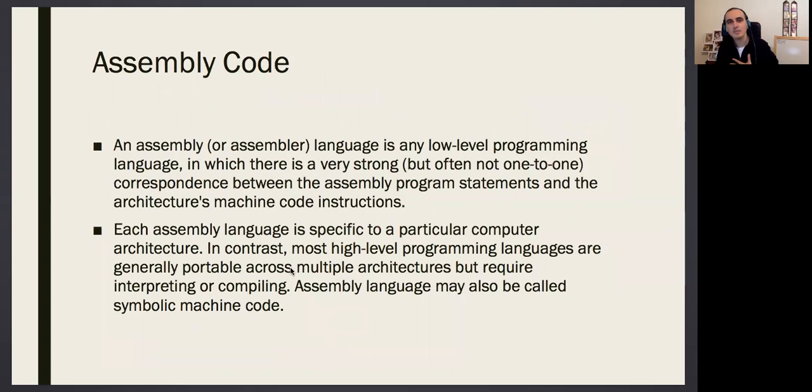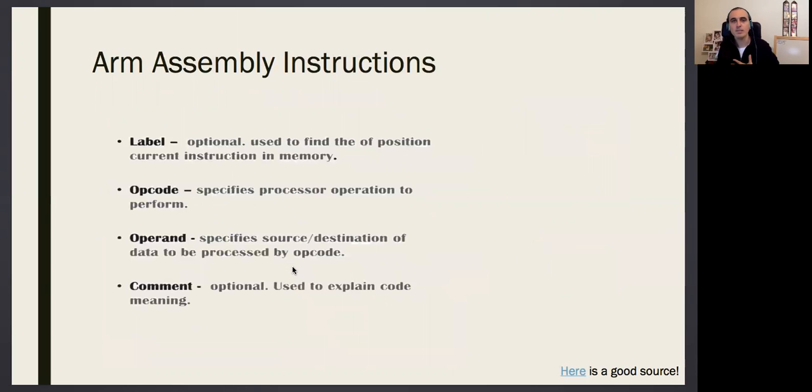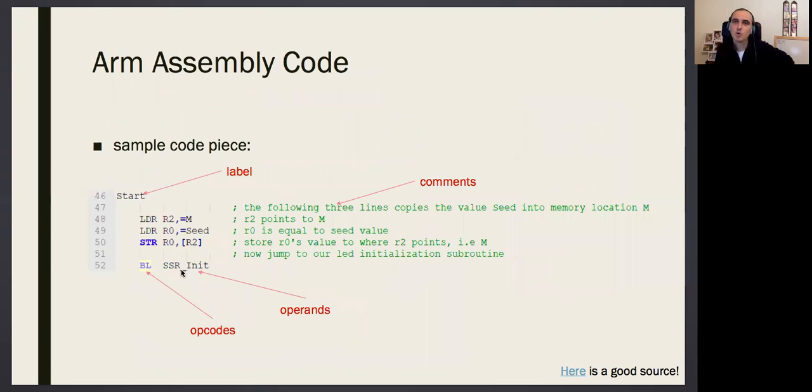You are saying, hey, assembly, I'm going to write this code, and you are going to put this code in the instruction memory somewhere. I don't know where you're going to put it, and I don't care. But you are going to start writing from somewhere, right? You are going to put the first line somewhere in the instruction memory. Well, that starting address, let's name it start. That's the beauty of it. Why are we doing this? Maybe we are going to jump back to it.